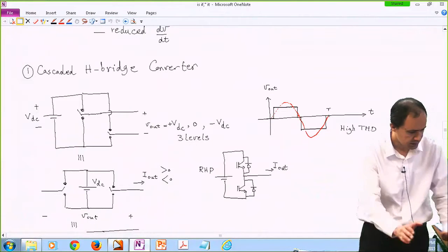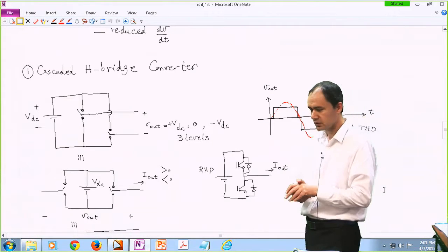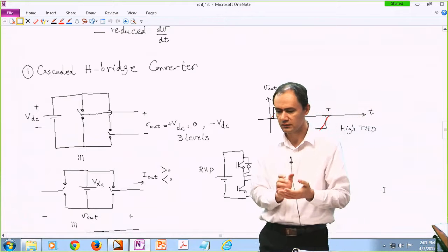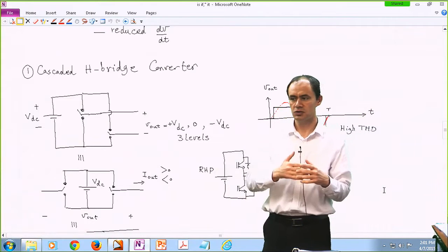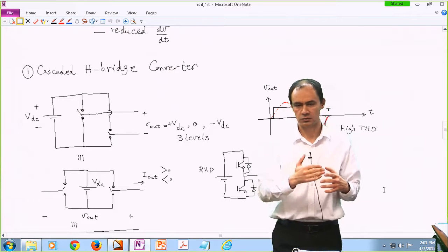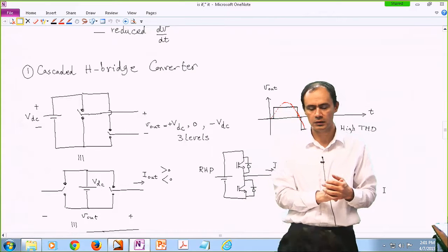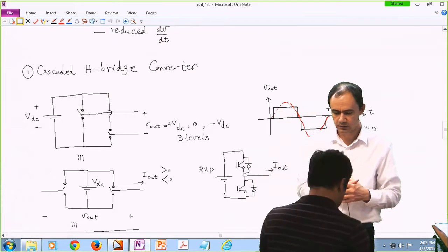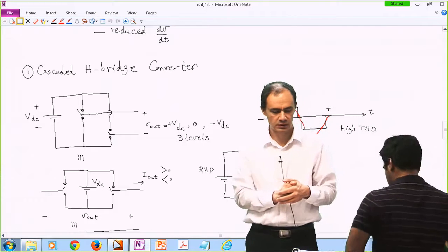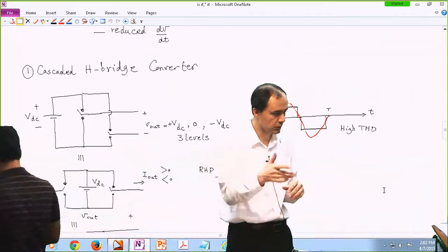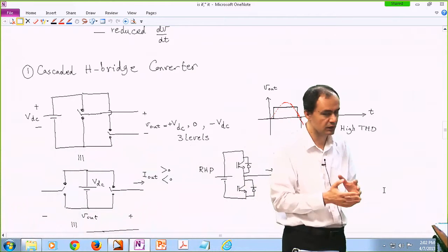So a classic single pole double throw switch gives us 2 levels of voltage. Your pole voltage is either, if the top switch is engaged, connected to the voltage of throw number 1, or if the bottom switch is engaged, then your pole is connected to the second throw. So you only have 2 levels.